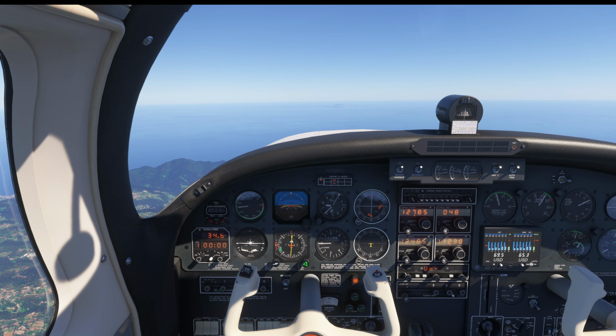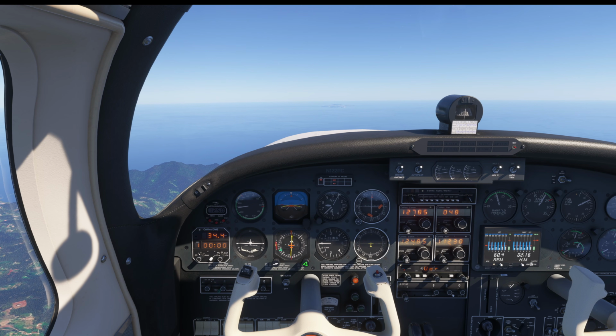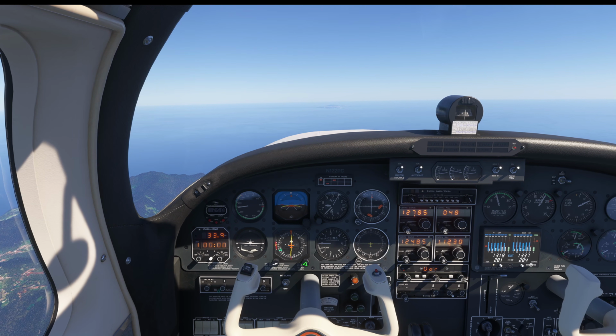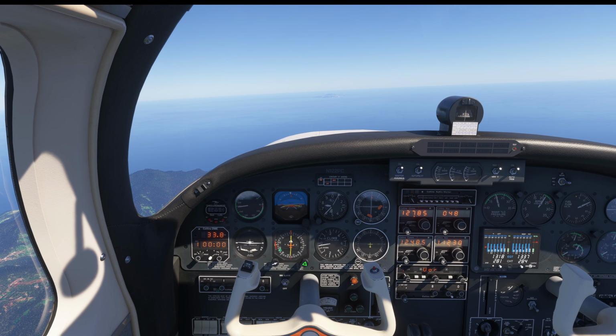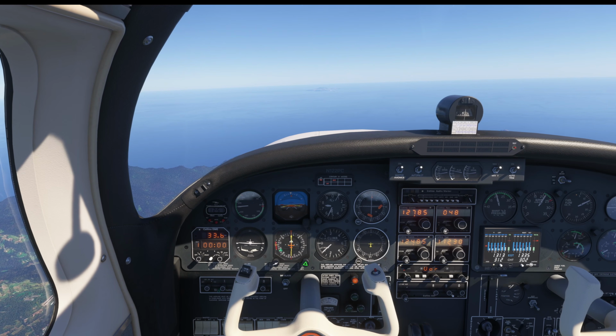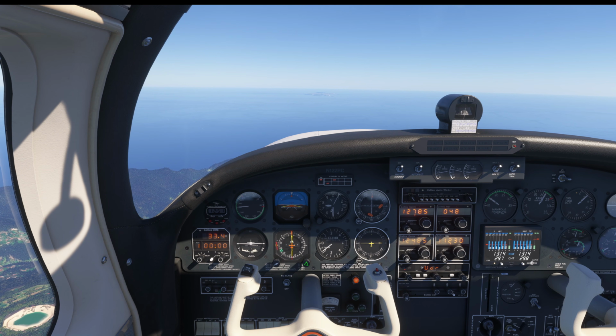For example, if I'm in altitude hold and I want to change the flight level, then instead of pressing buttons on the autopilot panel, I can just press the pitch sync button on my controller, push the yoke to set the new pitch that gives me the expected rate of descent, and release the button. That's it. Now I'm flying on autopilot again.